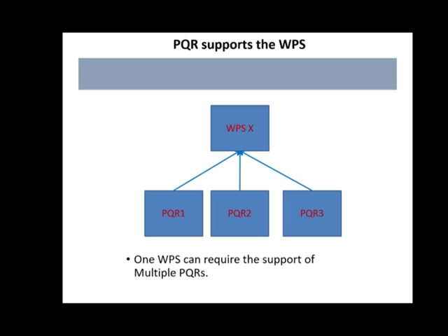You're asking, how can that be? Well, let's say I've got a whole library of PQRs, previous PQRs that I've done, and customer X wants a WPS written. He comes up and he says, Gary, I need a WPS so I can weld the root with flux core, the next pass with shielded metal arc, and everything from there on out, I'm going to use submerged arc. And instead of going and qualifying a procedure that does all of those, maybe I've got procedure qualification records, WPSs laying around that contain all that data.